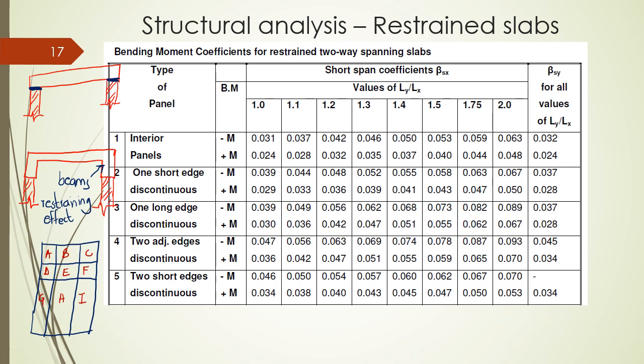is an interior panel because it has neighboring panels all around it. So panel E will be an interior panel. And I'll use the values here to determine the moments at the midspan.